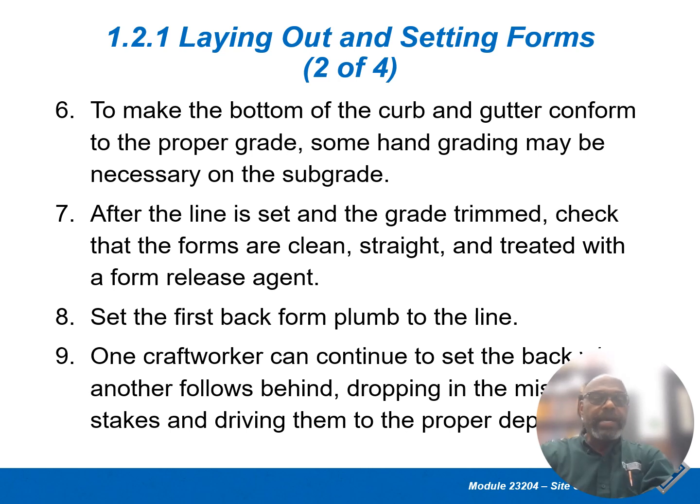After the line is set and the grade trimmed, check that the forms are clean, straight, and treated with a form release agent. Then number 8 says set the first back form plumb to the line, and then one craft worker can continue to set the back forms while another follows behind, dropping in the stakes and driving them to the proper depth.